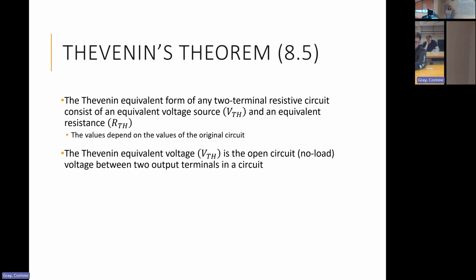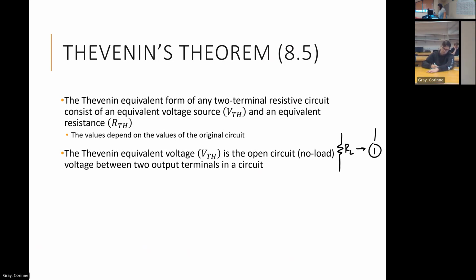A voltmeter measures voltage. In this class, the symbol we're going to use for this replacement is the V inside of a circle. We had our load resistor, which is going to become RL in our circuits. So it's just some way to read the voltage, and it is replacing the load resistor.